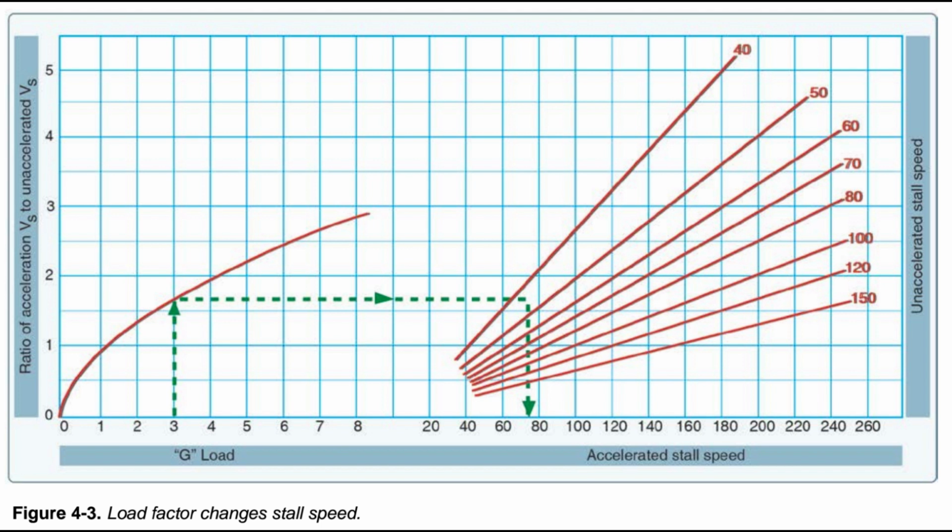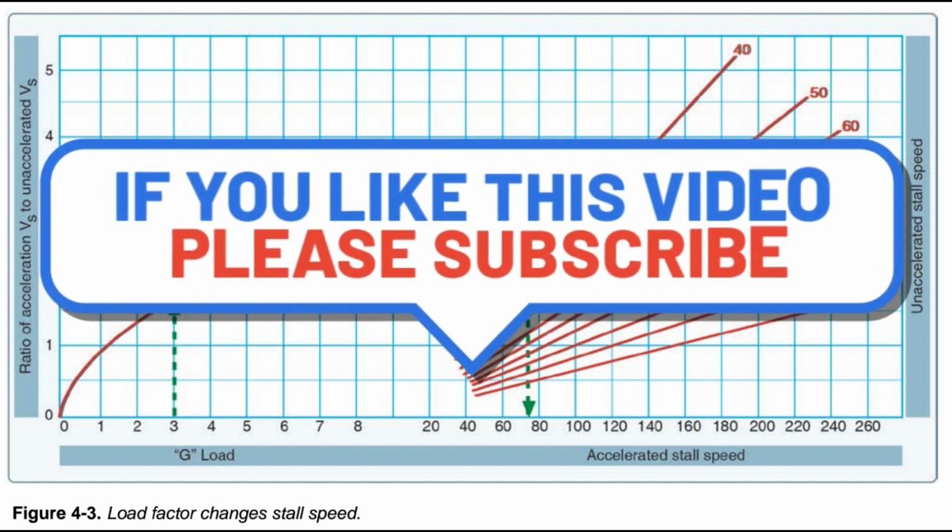10. Longer landing roll. The pilot must be knowledgeable about the effect of weight on the performance of the particular aircraft being flown. Excessive weight in itself reduces the safety margins available to the pilot and becomes even more hazardous when other performance-reducing factors are combined with excess weight. The pilot must also consider the consequences of an overweight aircraft if an emergency condition arises. End of page 33.